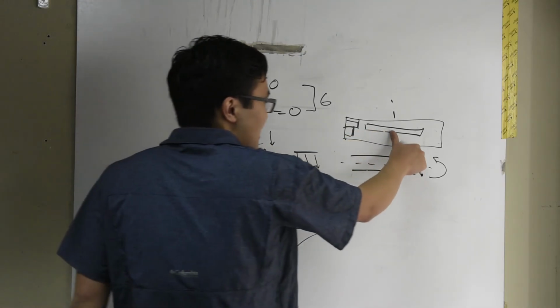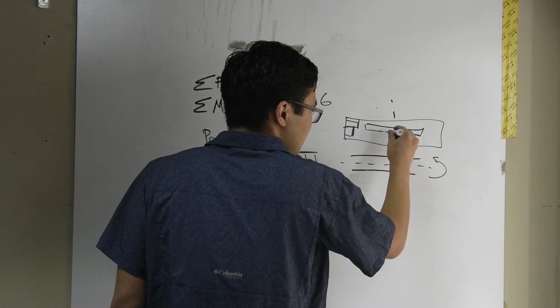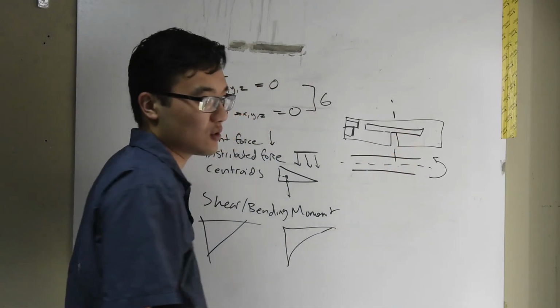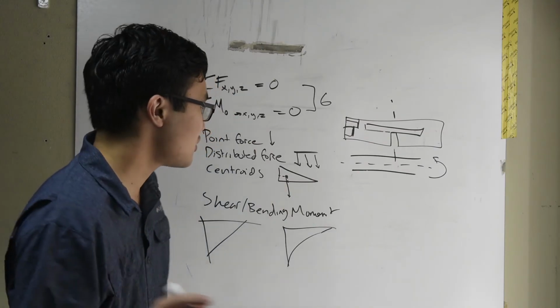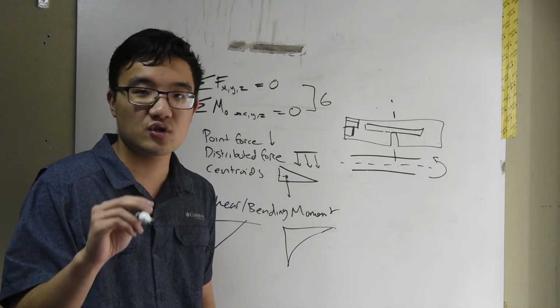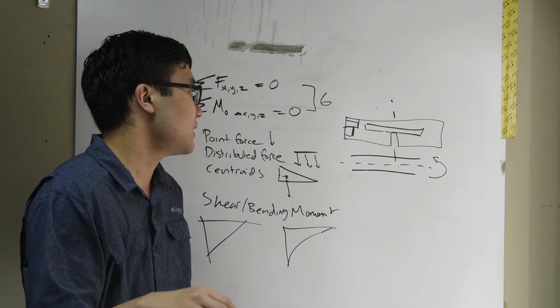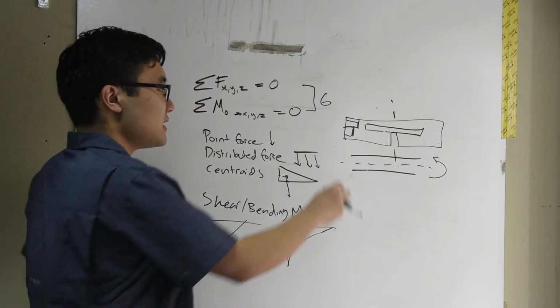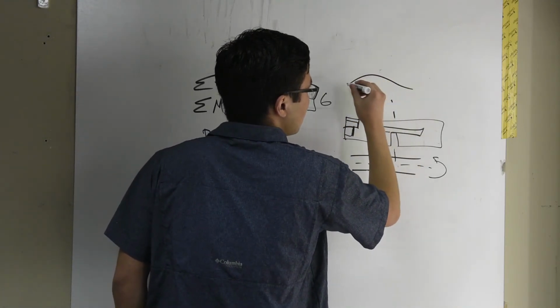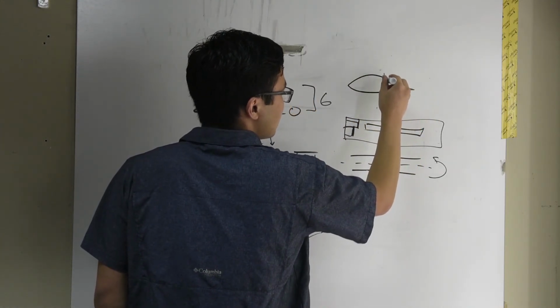So why did we slot the wing then? Remember? We had a giant hole cut in the wing there, which weakened this central part of the wing. That choice, while a poor one structurally, allowed us to do certain things with design. So we had to make that choice. But notice, we cut it out of the side profile of the wing. We cut basically into here.